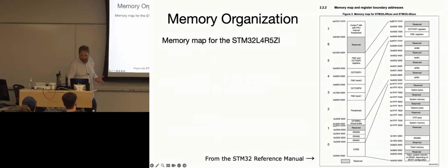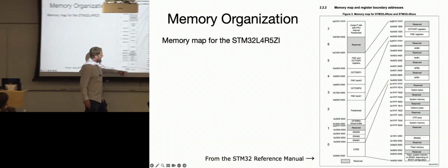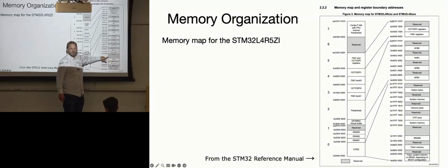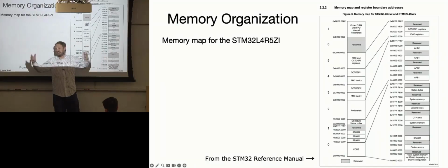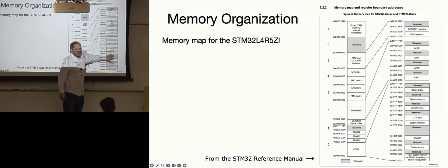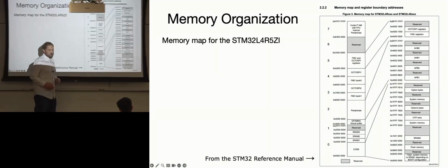So if we look at the specific microcontroller you're using in the lab, they have a lot of these reserved spaces. You'll see this in the datasheet. Reserved doesn't mean that it's there. Reserved just means they're reserving it, maybe for a future architecture where they're going to implement something here, or maybe in a different design. It's just not implemented. These addresses and this memory do not actually exist. They're just saying, here's boot, here's flash at this address, here's SRAM starting here, and up and up and up.